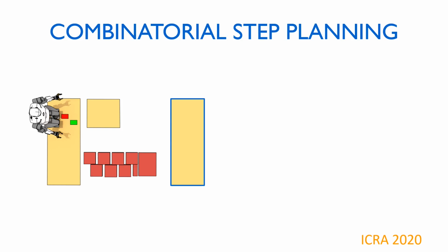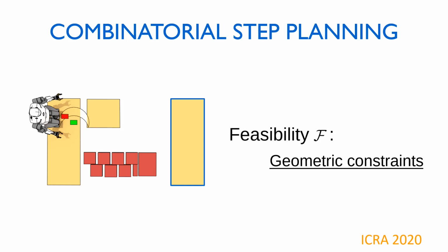Now ideally, we would like to make our next step on the second platform, here. However, we need to account for the feasibility of our contact plan. This crescent approximates the kinematic constraints of Talos. With the right foot on the green location, the center of the left foot must belong to the crescent to satisfy the geometric feasibility. It appears safer to backtrack our contact plan and place the first step a little bit forward. This allows for the third step to lie completely on the second platform.